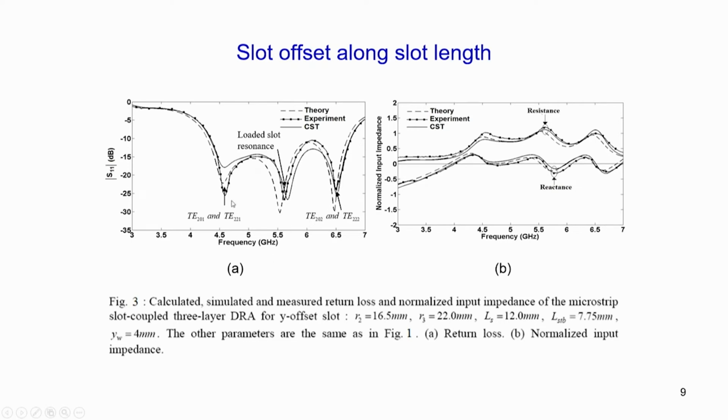So, you see how the knowledge of the modes enables us to focus on regions which might lead to the concept of the polarization purity of the modes, that is the extent to which the radiation characteristics of one mode is affected by or may be affected by the presence of another degenerate mode. So, we need to be aware of this, okay, and the knowledge of the modes helps us